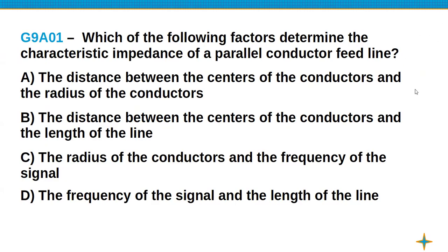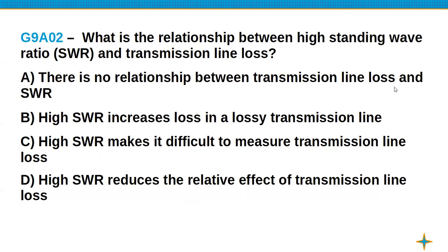It's not the length of the line. Correct. So as you separate them, the impedance goes up. Or if you use larger conductors, the impedance goes down.